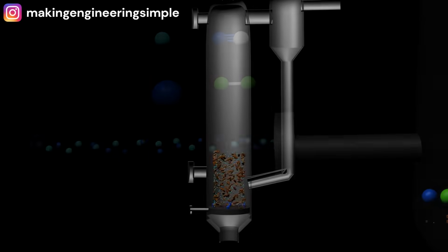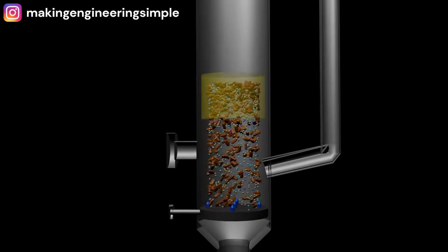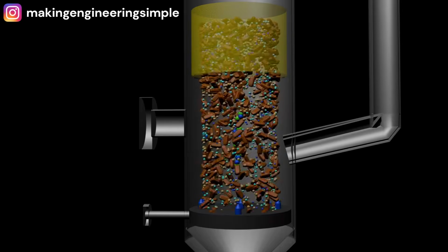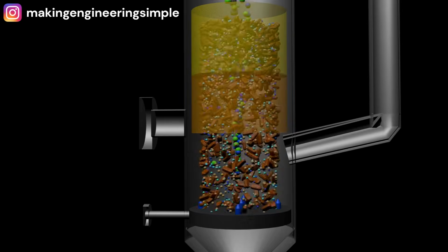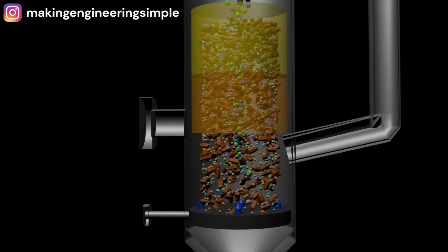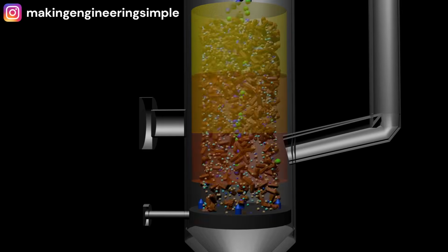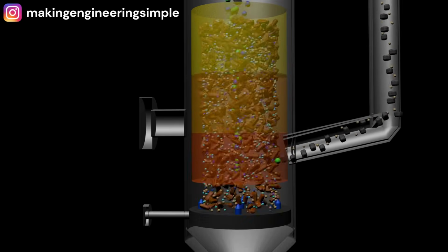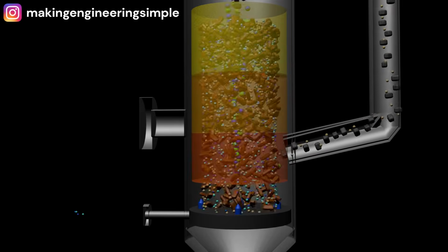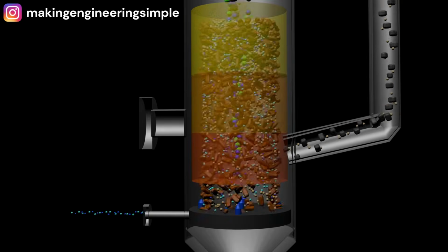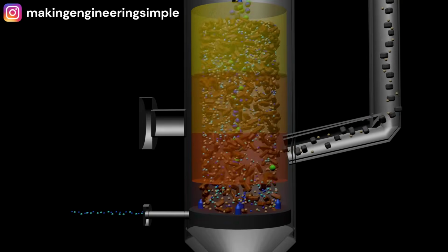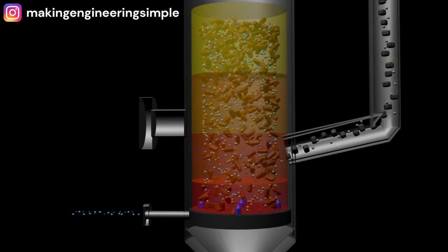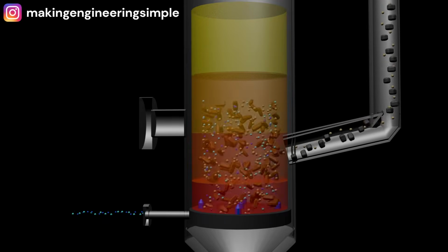As the fuel moves through the bed, it passes through several stages. The first stage is drying, where any moisture within the feedstock is driven off. The next stage is pyrolysis, which takes place when biomass is broken down into volatile gases, tars and solid char. Then gasification takes place, where char reacts with oxygen, carbon dioxide and steam to form carbon monoxide, hydrogen and some methane. Finally, at the bottom of the gasifier is where combustion occurs, producing carbon dioxide. Together, this mixture forms syngas.